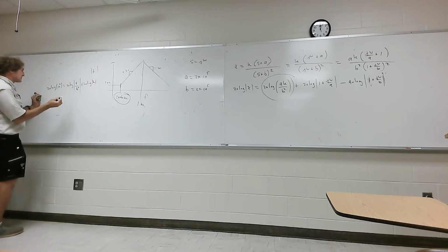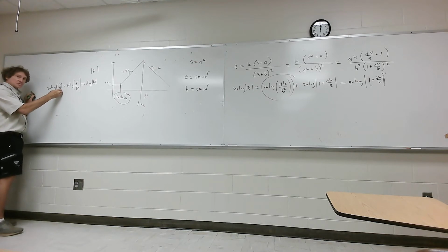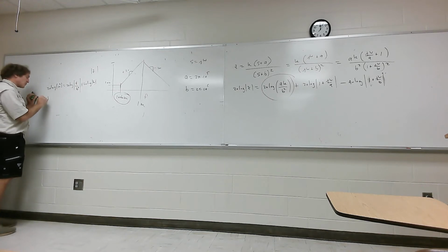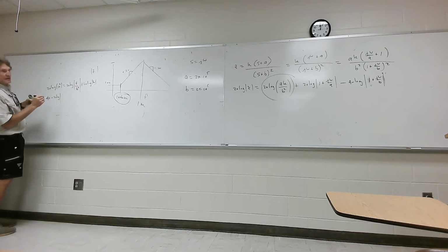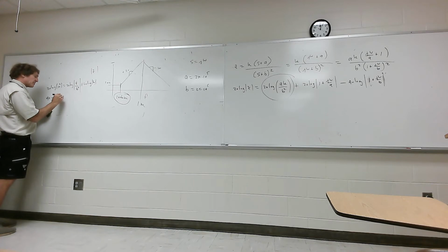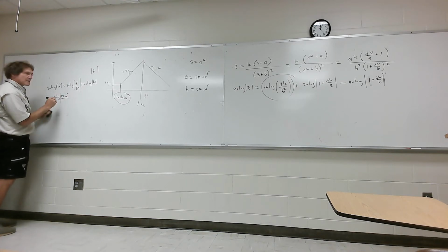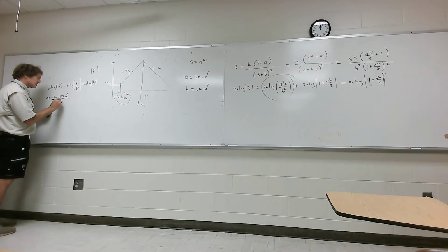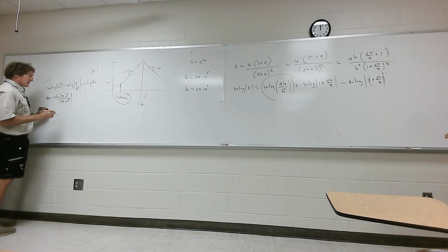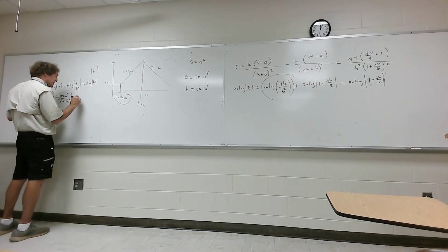So if you look at this, the log of 10 squared is what? Well, the log of 10 is 1, the log of 10 squared is 2, correct, class? Times 20 is 40, right? Then I'm going to take this, and I'll subtract that off, so it's 20 times the log here of the magnitude of A, and that's 2 pi times 10 to the 5th, over B, which is 2 pi times 10 to the 6th. But this one is squared, and this will be equal to 20 times the log of K,